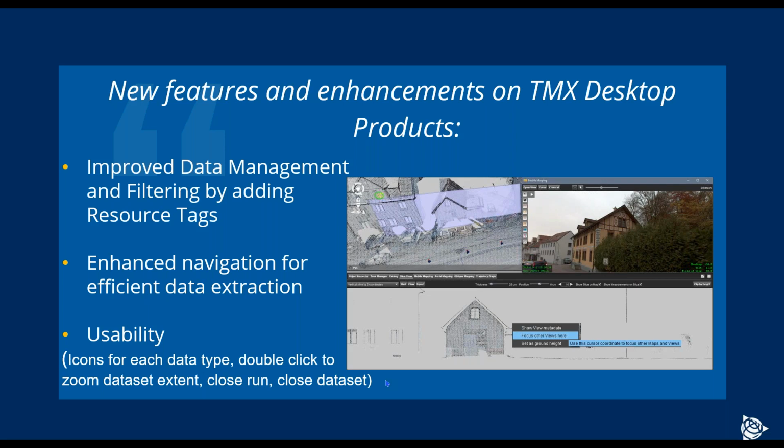You can see on my screen now, on Miguel's screen. You can focus on an object from multiple views and perform measurement or extraction out of any of them: 3D view, image view, or slice view in that case. And when moving along the trajectory or to a different feature, all of your views now can be synchronized and will be moved to the certain point together. Very efficient navigation for massive feature extraction workflow.